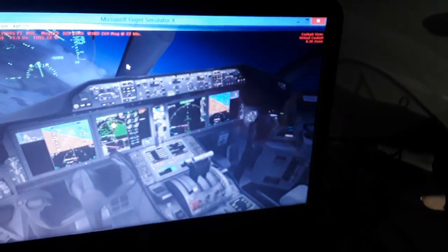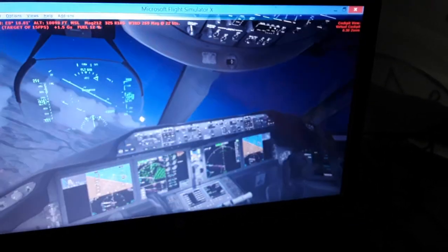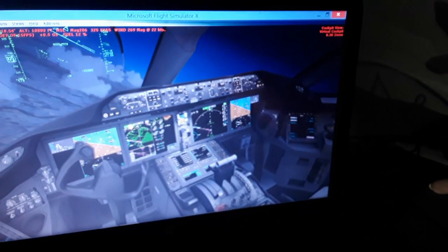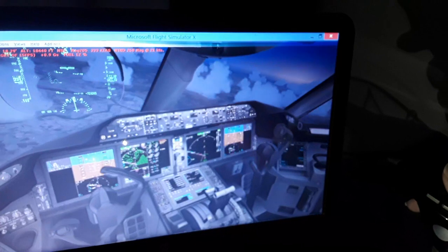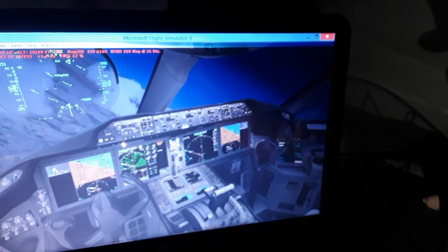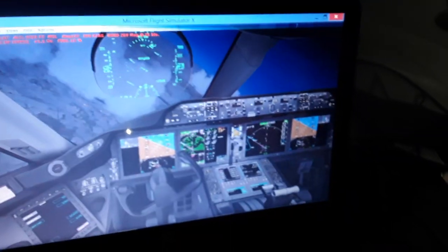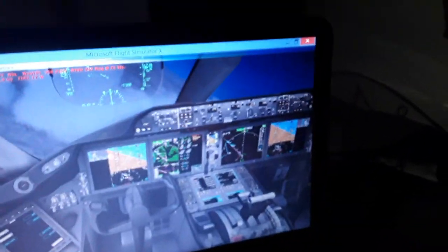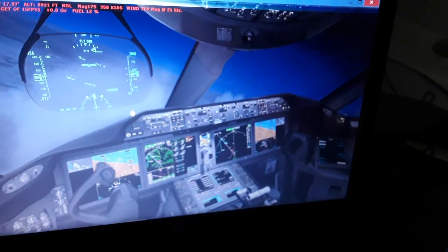So we have like 4 or 5 minutes more for approach and landing. The aircraft as we descend 10,000. It descends a little bit steeper. Use full left rudder now for this turn. As you can see, left rudder pedal, left rudder. We need to align with this line over here where is the runway. Also increase the rate of descent.